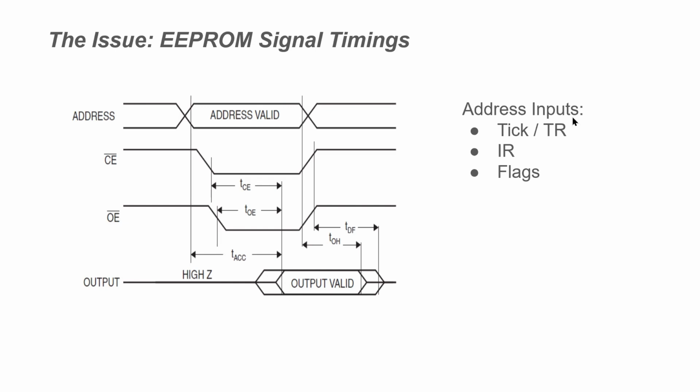And we have one other source of change for the address, and that's the microcode tick reset signal, right? That ends the currently executing instruction by resetting the tick counter, and that's obviously resetting part of the address back to 0. So again, we have that 150 nanosecond delay. So I think you can start to see that those are two significant issues that we have not addressed at all in our current